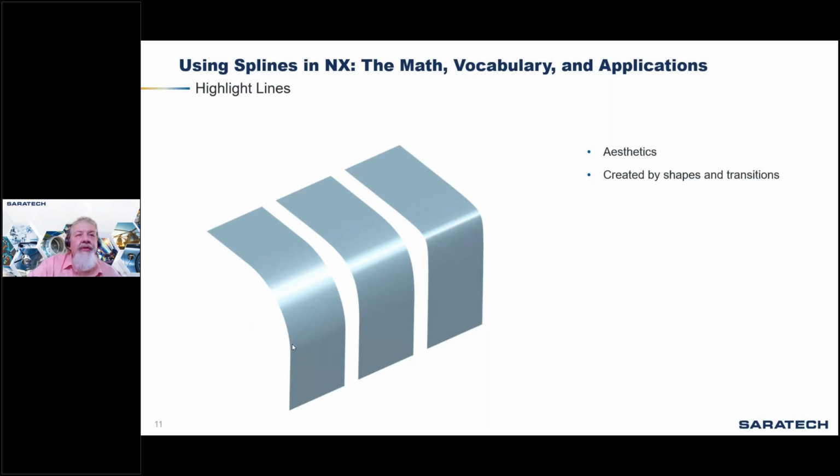If we look at the first example on the left, here we're using a tangent constraint. If we had used some splines to help define that transition from the top sheet to the bottom sheet, we have that curved transition in between. If we're using tangency, you can see that we've got a much more flushed out kind of highlight on that surface. And in some cases, it can actually look like a hard line where it makes that transition from the flat sheets into that curved surface. It's kind of hard to imagine, but you can actually see a line.